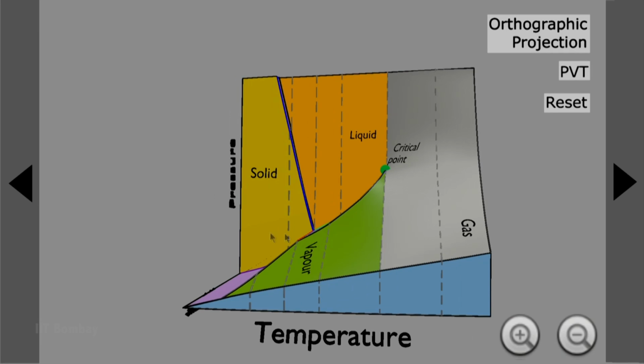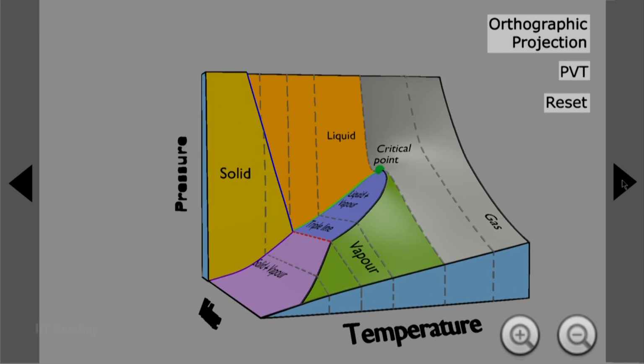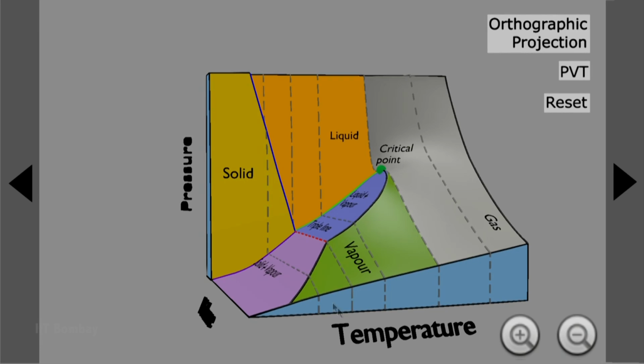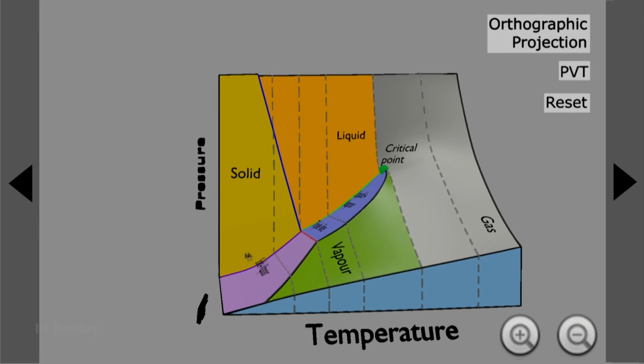So there is a phase transition line between solid and liquid and between liquid and vapor region here, and the vapor beyond a critical point, I normally call gas. This is what we sometimes call superheated vapor also. Also, what you can see from here is that if the pressure is much lower and the temperature is low, the solid can get transformed into vapor directly, and again there is a phase transition line over here. This is a direct transformation from the solid phase to the vapor region across this phase transition line.